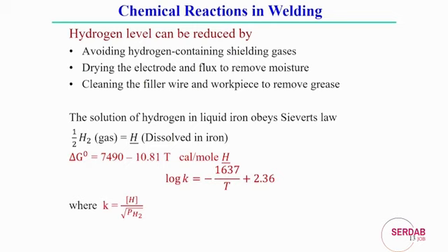But of course, the presence of some amount of hydrogen during the welding process simply follows Sievert's law. Here we can find similar kinds of equations, and all the equations are given. We can represent the free energy in this reaction, which also depends on the temperature and the partial pressure of the hydrogen.